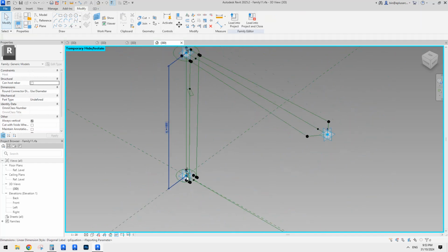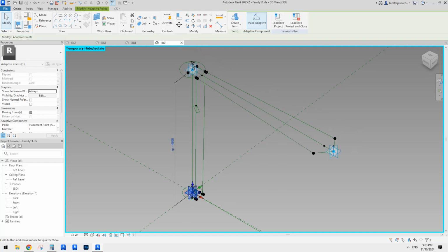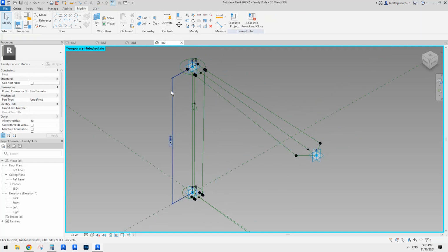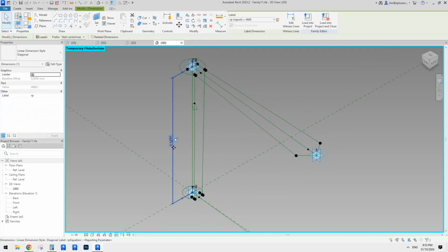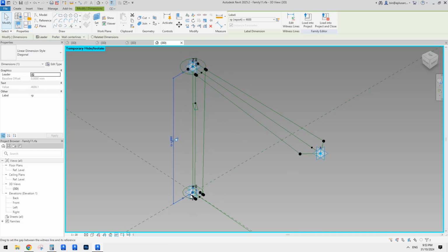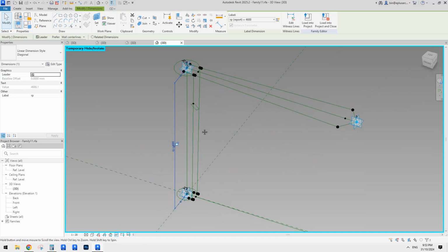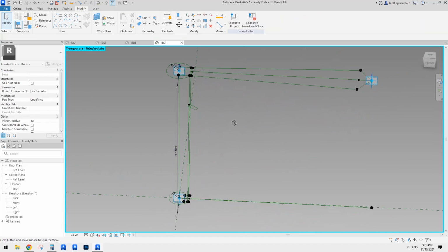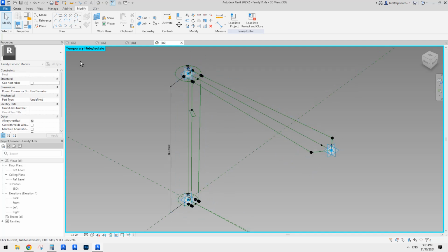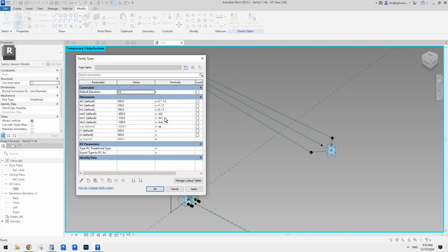Between adaptive point 1 and adaptive point 2 there's a reporting parameter to measure the distance, the height difference between point 1 and 2. So this is a height reporting parameter. And actually, what's this for? Do we need a reporting parameter? Okay, so that's a negative reporting parameter.